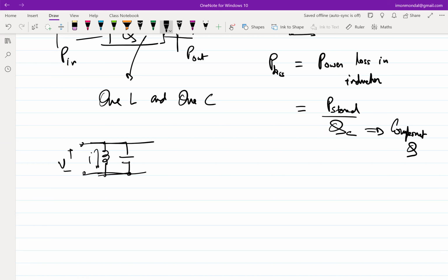They are 90° out of phase. So if I have a current maxima, then I have a voltage minima. If I have a voltage maxima, I have a current minima, and so on. So to find the total energy of the tank, I can find the maximum current in the inductor, and half L I squared is the energy of the tank.